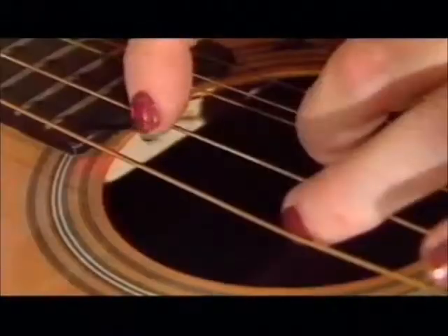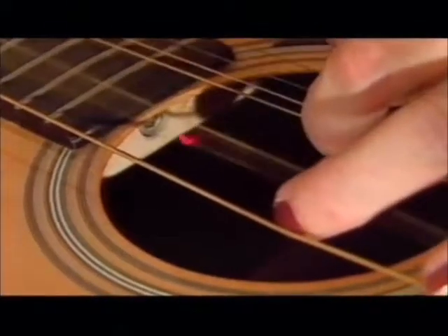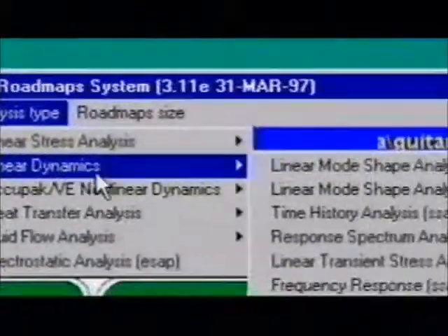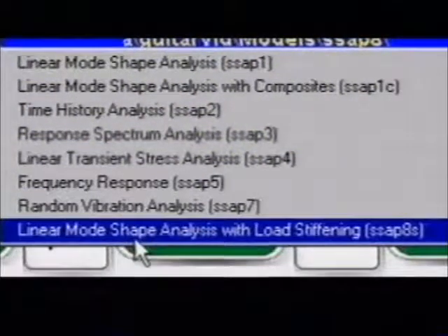In an airplane or car, loads or forces, and therefore natural frequencies are constantly changing. Therefore, to predict the dynamic response, you must consider load stiffening. Algor offers 2 ways to predict frequencies as a result of load stiffening. The first way is with the vibration level 2 extender.